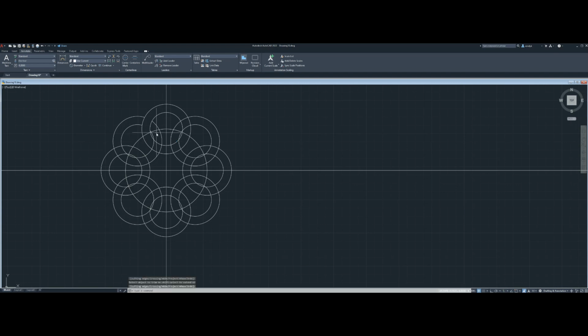I'm going to cancel this, delete this circle for a moment. It would interfere with what I'm trying to do. Enter trim, TR. Press the spacebar twice. So I want that one above this one. This one like that. This one like that. So I have my first ring that is visually comprehensible.